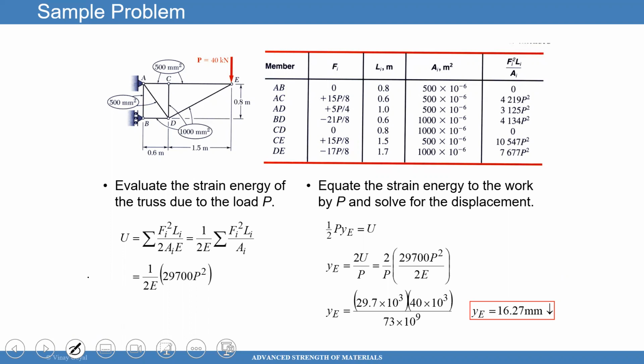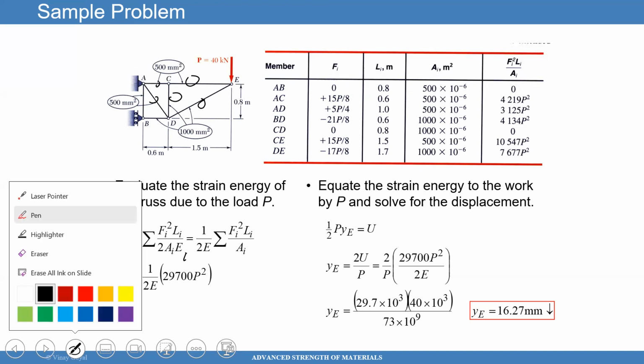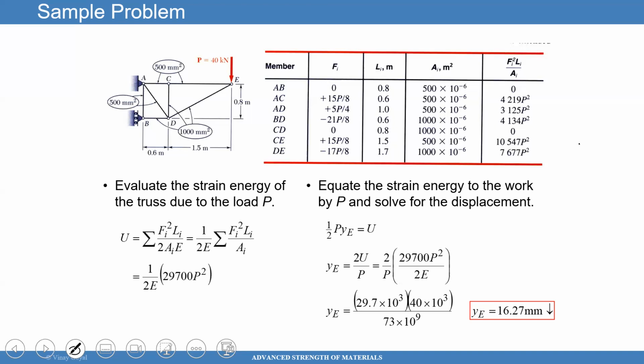You can also have different modulus. I could tell you in the exam, oh, listen, this bar and this bar have a modulus of aluminum, but this bar and this bar are steel, for example. Then what will change in everything I did? Where? In what calculations? Where will you change anything? Where I'm adding them up, 20 points for you. You put the modulus here, E_i right there. So every single thing has a different modulus now. This is cool. You can have different lengths, different areas, different modulus, and I can tell you using energy what the deflection was at that point. And I don't know of other methods that can do it so clean, okay? Except for finite elements. If you take my course in finite elements, you will see that this is done in an even easier way. Please, question from you.